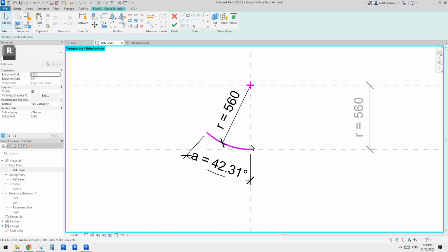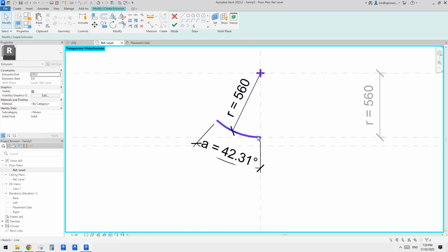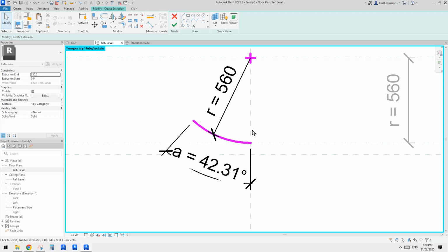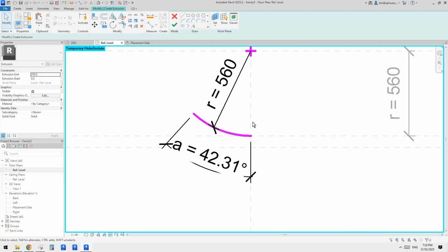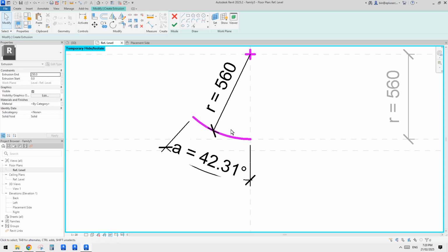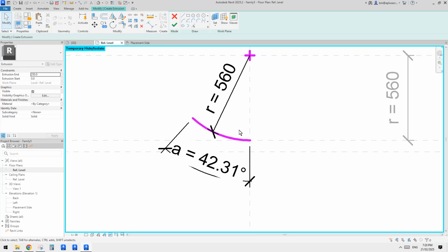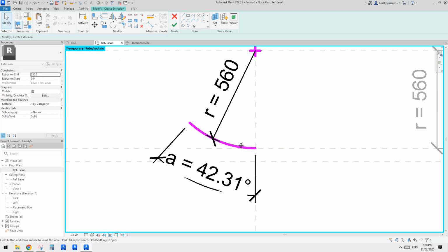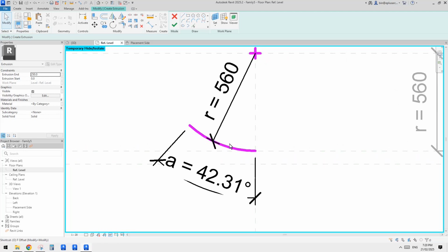But this is only one line. To create an extrusion, we need a closed loop, right? So it's not one line. What we're going to do is, actually, if we use a sweep, we can probably just use this one, but that doesn't matter. Let's just use extrusion. Now we need to offset. So create an offset, OF, type OF.